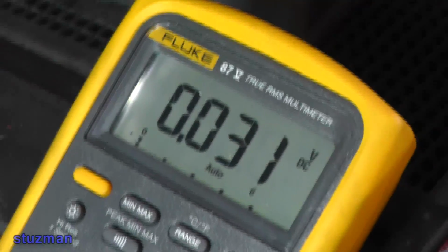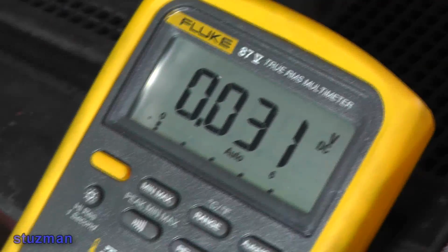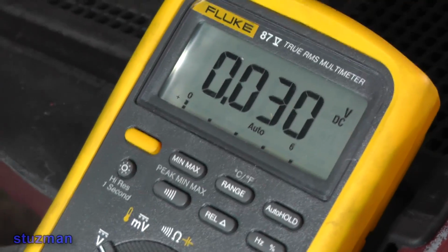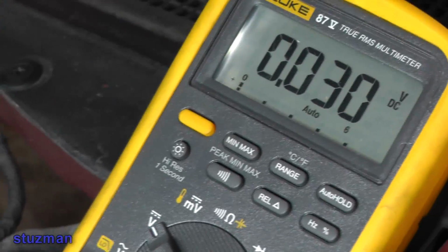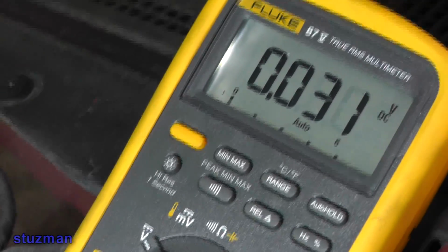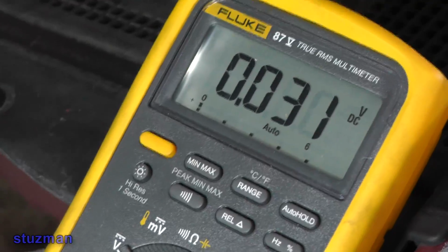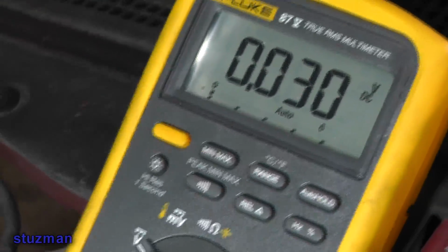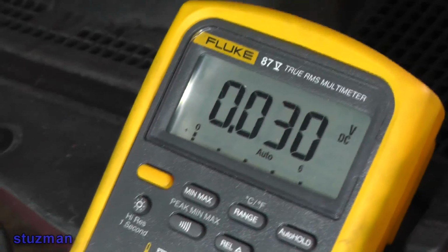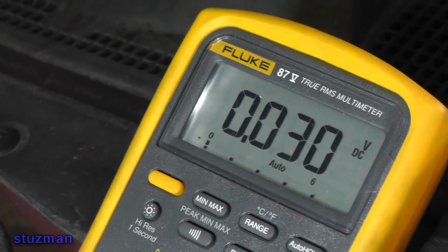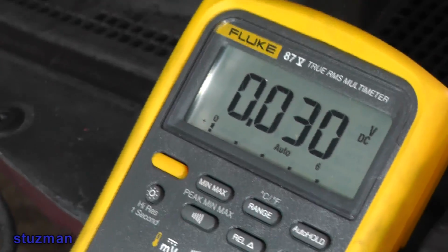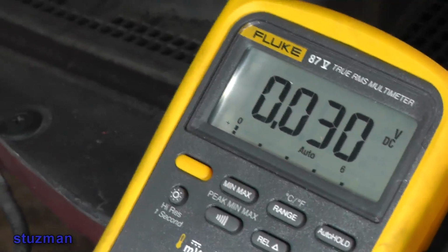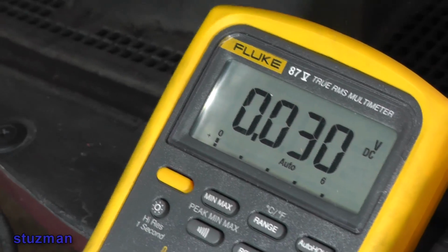And what do we see? 31 millivolts. That doesn't make sense. Well, what doesn't make sense? Well, I thought the closer to 0, the better. That is exactly right. But this one's new. So which one is the better relay? The old one. The old one is better. Doesn't make sense, yeah. So there you go. The old relay contact is better after 17 years. This is a new relay. I mean, there's nothing wrong with it. As far as we know, under 50 millivolts is what I use as a standard here.